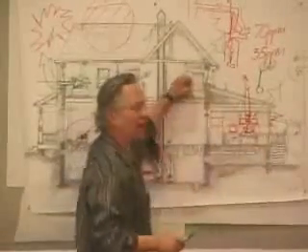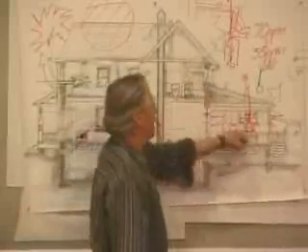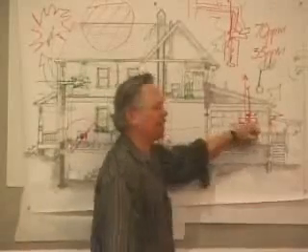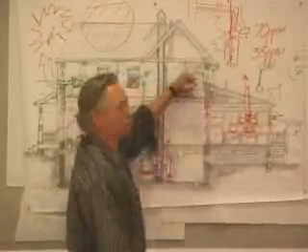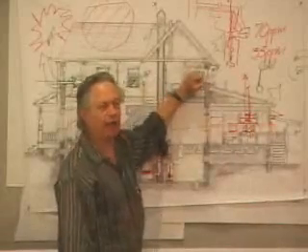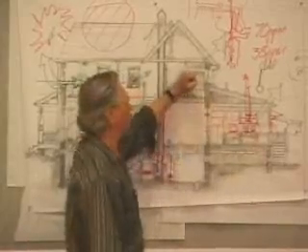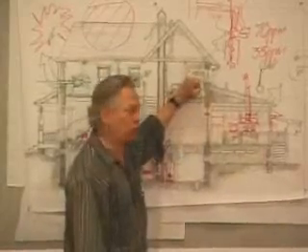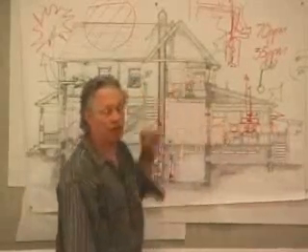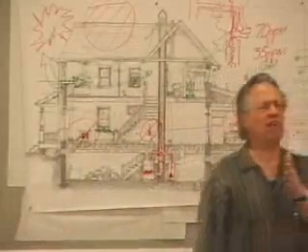The kitchen and the bathroom both have moisture problems. The kitchen has moisture problems, it has grease problems, and it has carbon monoxide problems. Here it's mostly just moisture problems and odor problems. But we want air moving through these rooms. Not a whole lot of air up here, enough. We would like to be able to control this air. We want to be able to turn this fan on and off. So if someone takes a shower, when do you want the fan turned on?